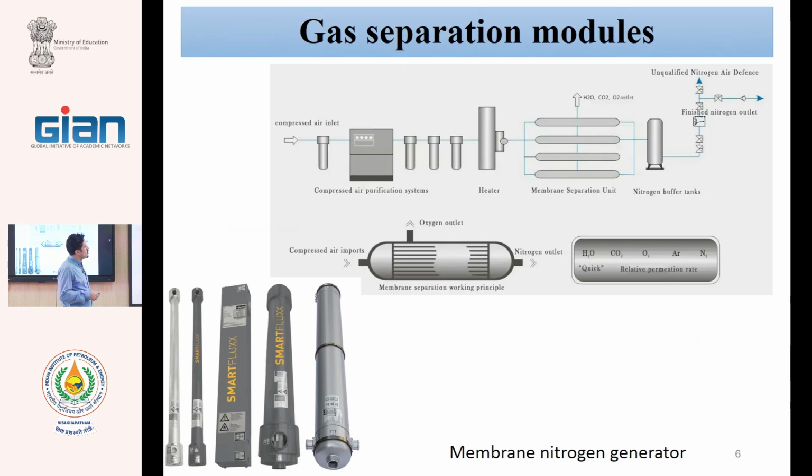And this is a usual gas separation unit. You see these cartridge filters with different micron sizes, for example 10 micron, 5 micron, and 1 micron, for separation of solids from the inlet. Because even one particle can cut the membrane surface like a knife, and the membrane will be destroyed.